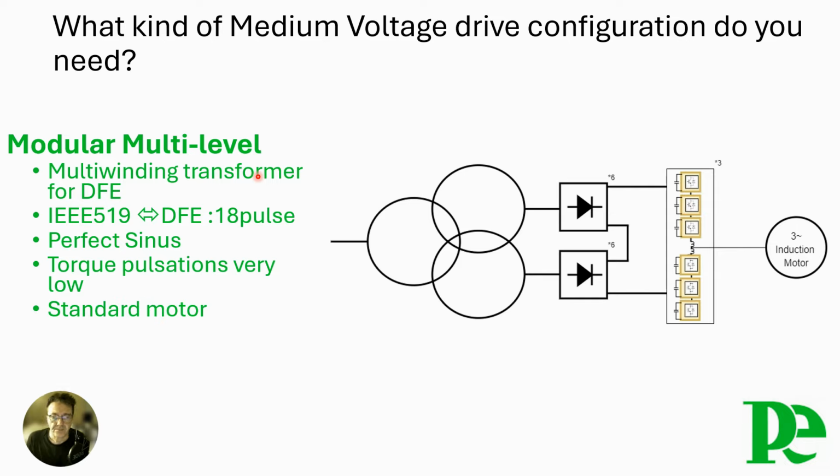These kinds of drives are widely used in general purpose applications such as pumps, fans, compressors, uphill conveyors, extruders, kneaders, mixers, crushers, excavators, and the list goes on: high pressure grinders, vertical and horizontal mills, blast furnace blowers, propulsion, thrusters, boiler feed pumps, agitators, presses, wire rod mills, forced draft fans, induced draft fans. In this configuration, the drive has no energy recovery capability.